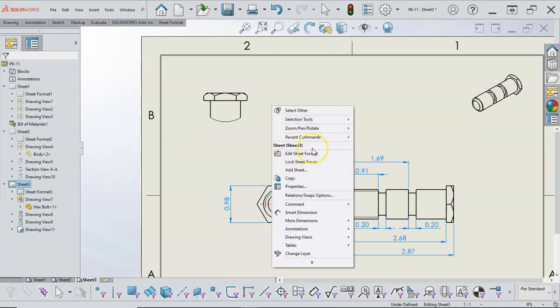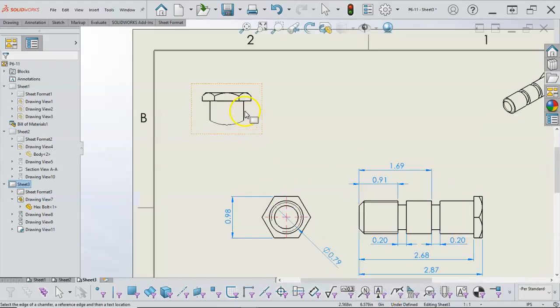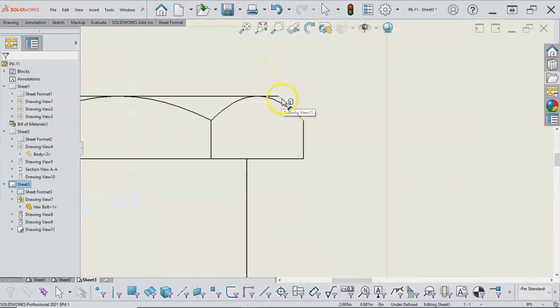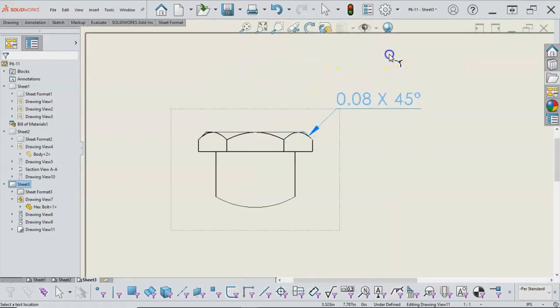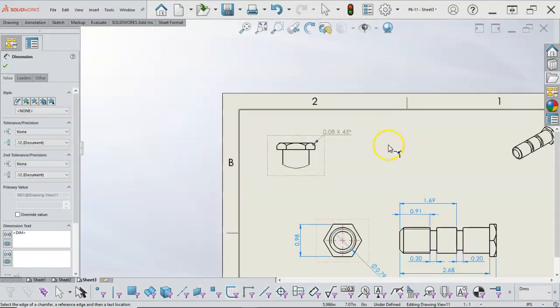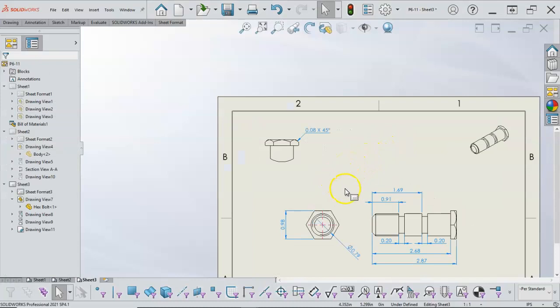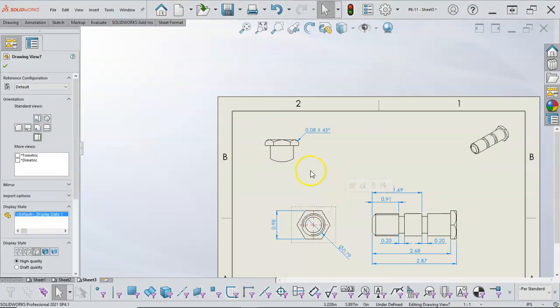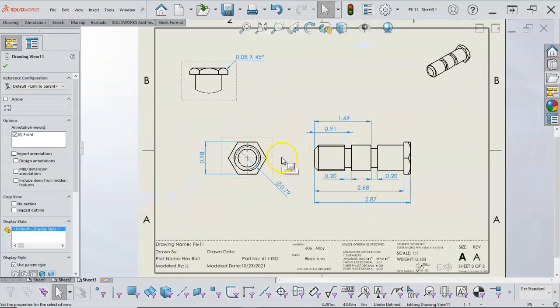And then when I dimension for the chamfer, we'll see if the chamfer will apply to that, since it wasn't specifically meant to be a chamfer or generated with the chamfer tool. So 2 millimeters by 45, and that could be assumed to be all around. All right, so these are kind of optional views to help generate the geometry. I could also try and rotate this, and this would be a good example to close on.